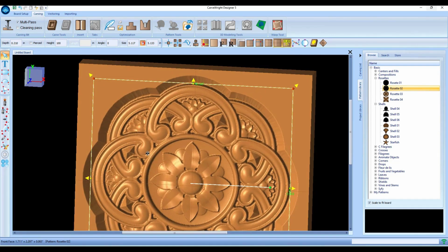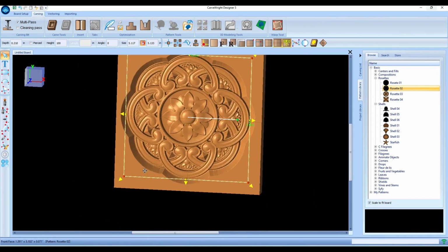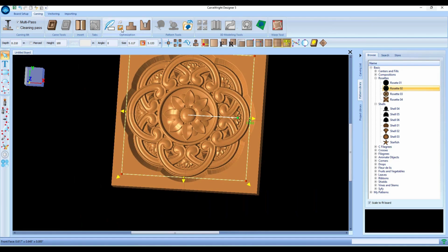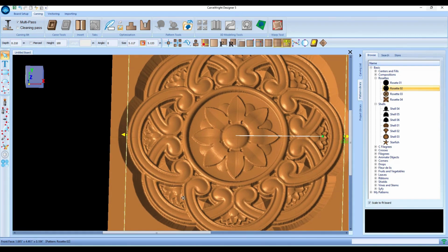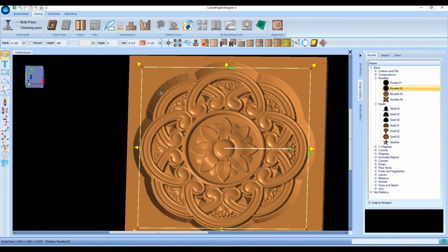Now, next to the feather selection up here, we have another icon. If I hover over this, you'll see this is floor feather. You can see the feather icon is pointing towards the bottom of the pattern. What this function does when it's highlighted is make sure that the feather starts uniformly at the same depth, essentially the base of the pattern around the border.